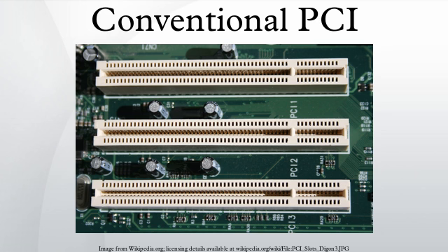100x, reserved, a PCI device must not respond to an address cycle with these command codes. 1010, configuration read, this is similar to an I/O read, but reads from PCI configuration space. A device must respond only if the low 11 bits of the address specify a function and register that it implements, and if the special IDSEL signal is asserted. It must ignore the high 21 bits. Burst reads are permitted in PCI configuration space.